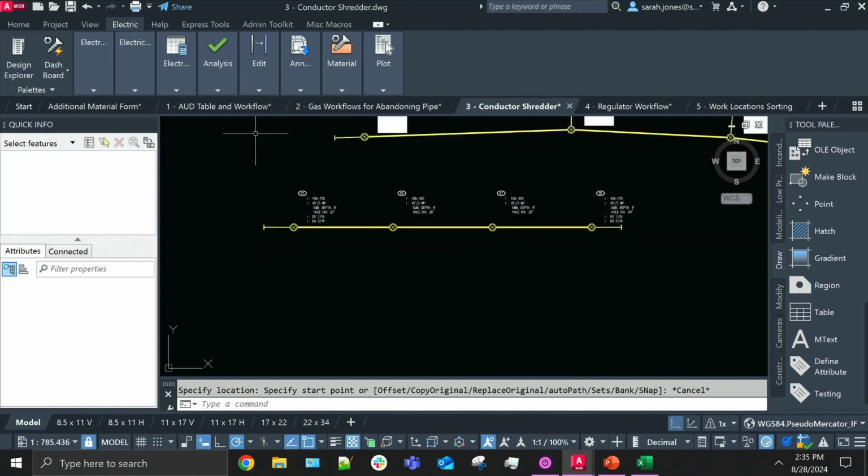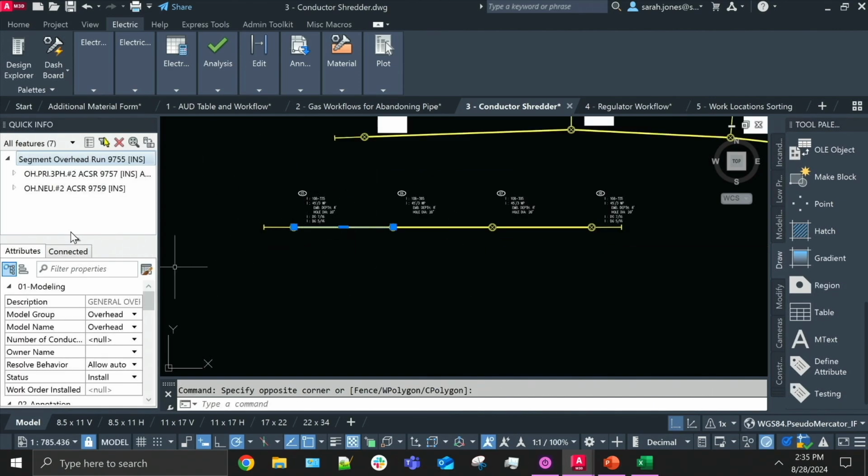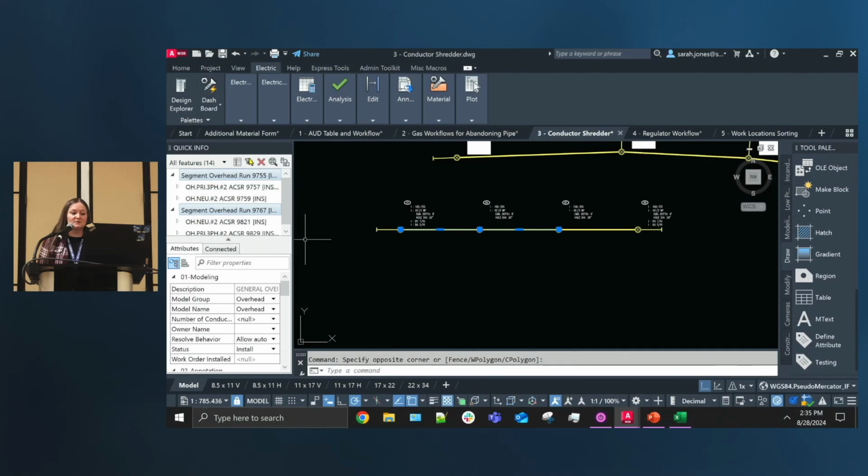All right, so there we have our pull line, and if I select each conductor now, if you look at the FIDs, there's 9757 and 9821. So this is really neat, because I think a big thing worth pointing out is you need an electrical device to tap an electrical line, a conductor. What's really neat is the electrical device gets auto-created, it taps the line, and then the validation, in these steps, deletes the electrical device, which is great because you want to limit the number of features you have to see in feature info, right?